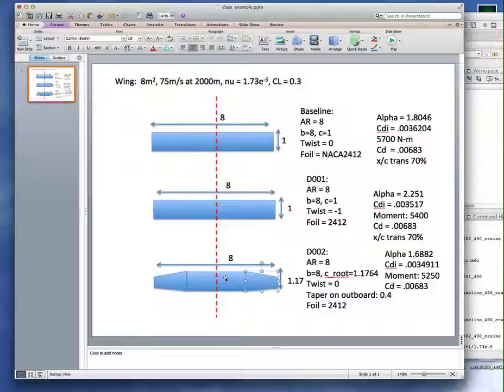And realistically, these wing designs are trade-offs. The higher aspect ratio is better in terms of induced drag, but you have fighting structural issues, essentially. I put it in as a simple constraint, which is two constraints: a bending moment maximum at the root, and number two is a thickness to chord constraint for your project. So that's it. Hopefully this will guide you.